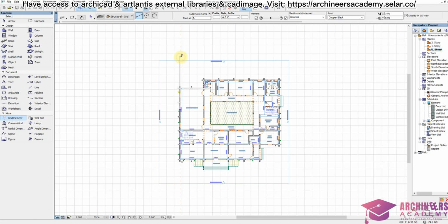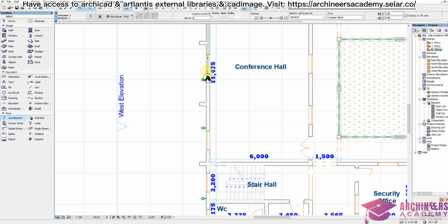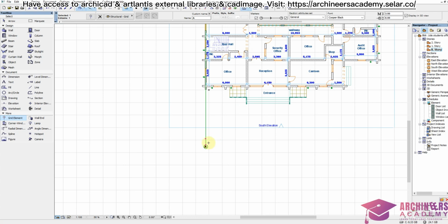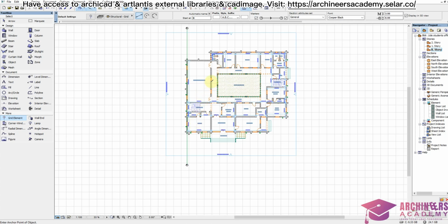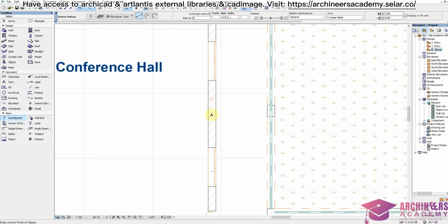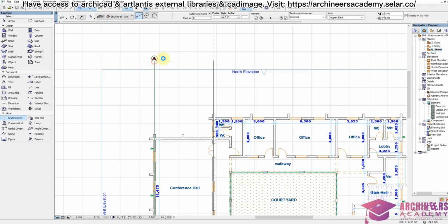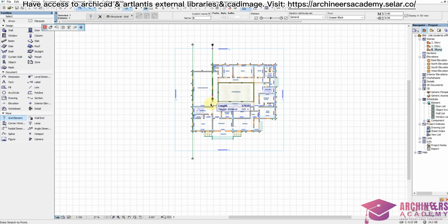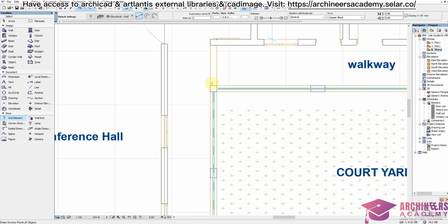So I'm going to extend my grid out a bit for external dimensions. I'm creating a very good space to place my external dimensions. So I want to stretch this also. So I've placed grid A, or grid AA has been placed. I'll move to my next wall to place grid B. So this is a mark also. I can follow any of those two methods. So grid BB has been placed. So we have grid C now.